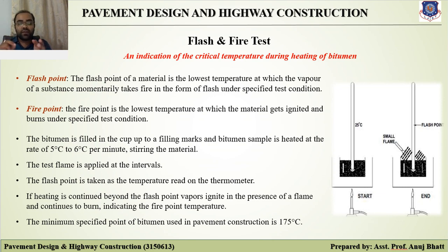So that means this flash point is to be considered when you apply a flame and it causes a bright flash in the interior of the cup in a closed system. At that moment, this particular temperature is known as the flash point. The minimum specified flash point of bitumen in pavement construction is 175 degrees Celsius.